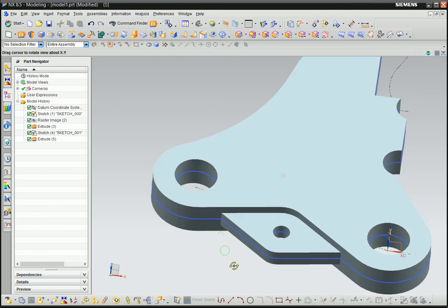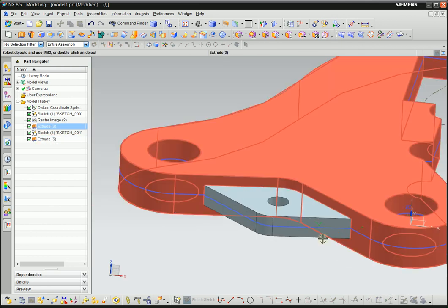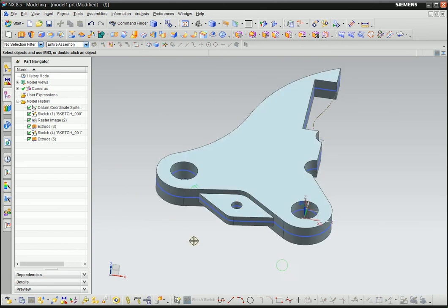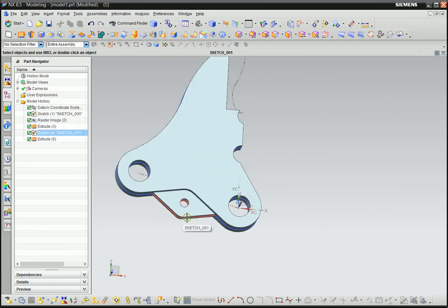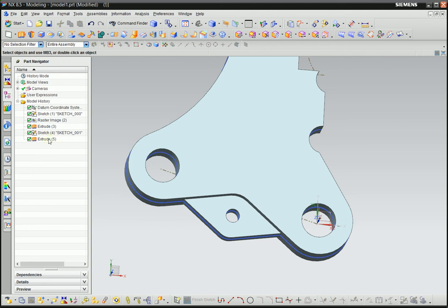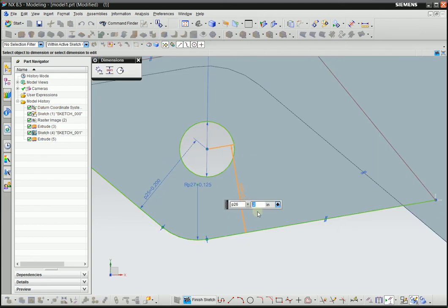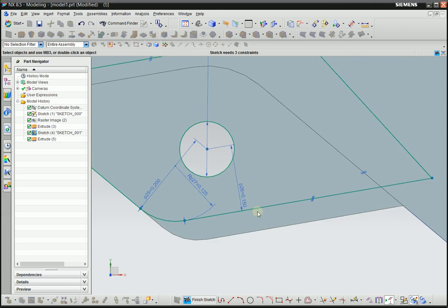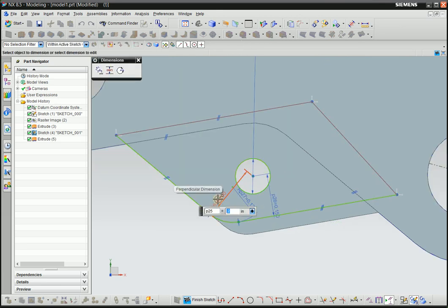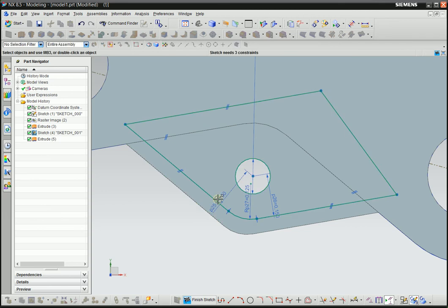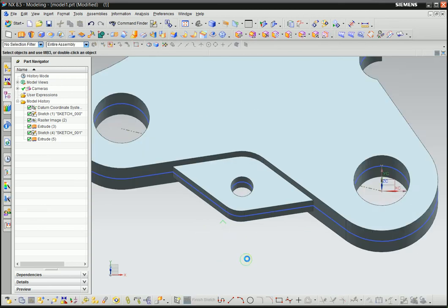Click OK. Let's have a look. That's your little ear. And it's kind of bigger than the one in IGS, so not a big fan of too big. So let's adjust it, and we can adjust that to 0.15 and finish sketch. It's automatically updated.